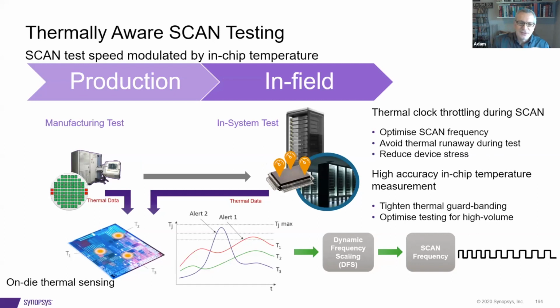Yeah. So yes, when you shift in, you have the shift-in switching activity, and then there's a capture operation which might change some of those bits. Again, we're using clock gating to turn off capturing. So if we've done a good job of filling and that domain has not captured, then we can unload the same data and it also shouldn't switch so much.